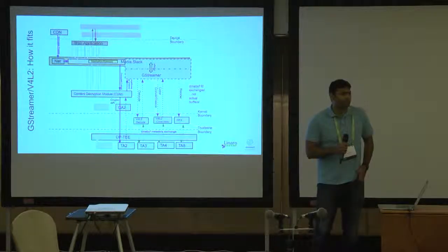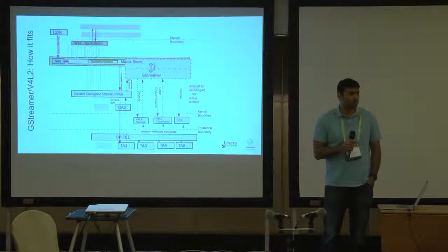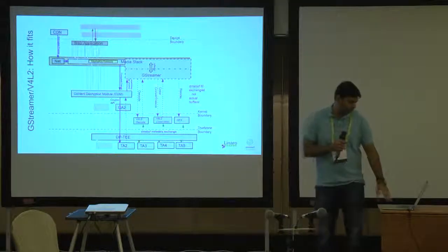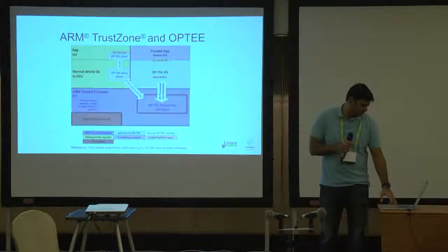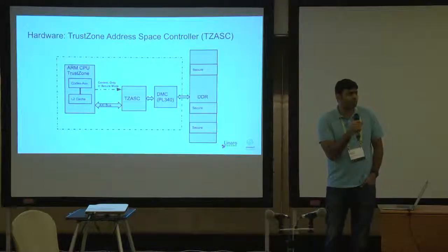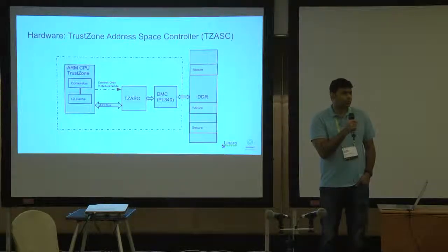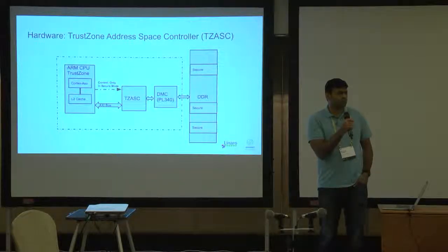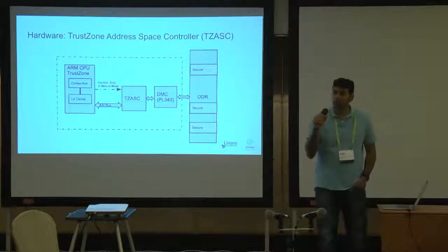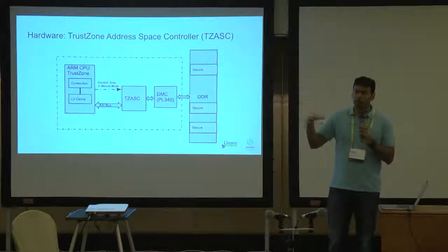Okay, I have a couple of questions. Number one, that slide that you showed on that DDR separation, right, where the TrustZone address controller, actually we have to give the area specific to the DDR that this is a protected area, right? Where the secure data will come. Now, do you have to do it at boot time, or can I dynamically change the address limit of the secure DDR? You have an answer for that, Gil? I'm sorry. His question was, how do you carve that out? Is it a carve out at boot time, or can it be allocated at runtime?